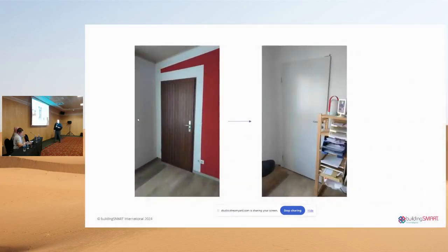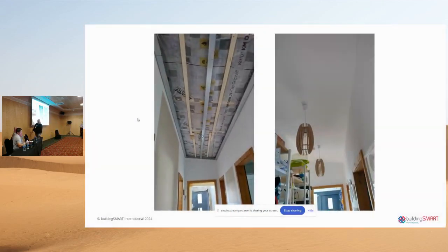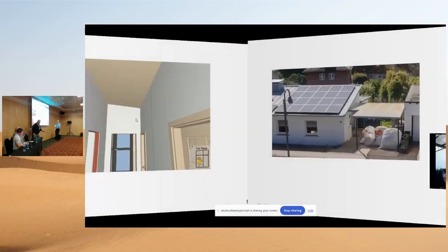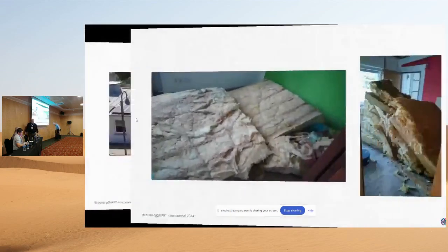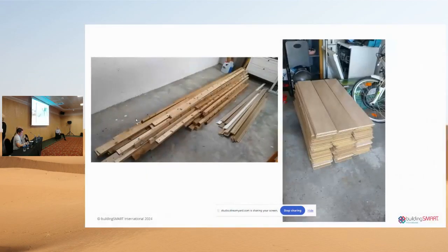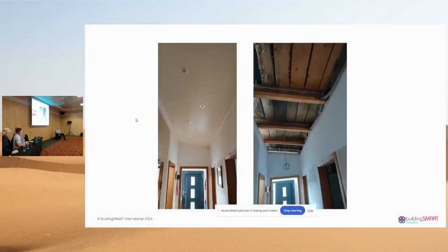One interesting point here, if you check behind, we have material that we had to consider a cause for mold. Airtightness itself is good, but if it's not properly done, it will potentially cause problems. So the new membrane should be open diffusion.